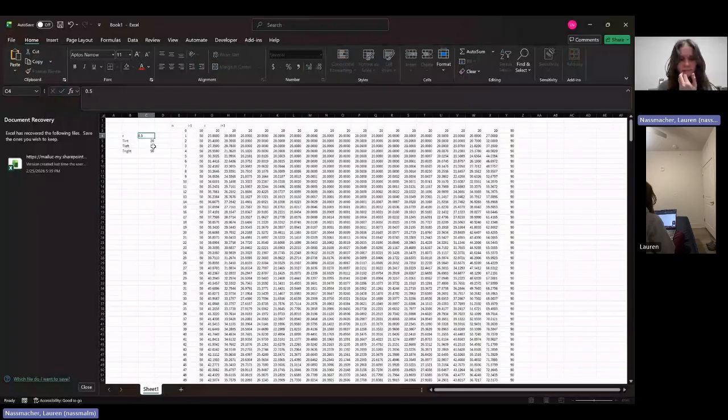So from this lesson, you should have learned a few things. The first one being that we can use a finite difference equation in order to determine a numerical solution for the temperature of the heat transfer for a rod. Second is that our initial condition and boundary conditions both affect our numerical solution very heavily. The third, that our stability relies heavily on our key parameter R, which is equivalent to the thermal diffusivity multiplied by the change in time over the change in distance squared.